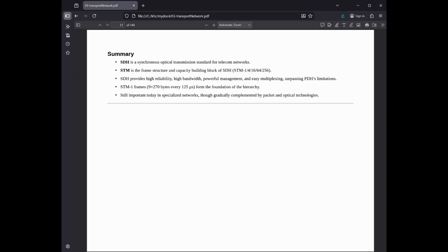The solution: FGOTN allows the network to carve out tiny, fixed-bandwidth hard pipes, down to 10 Mbps, inside a 100G or 400G wavelength. The goal: it allows carriers to finally turn off their old, power-hungry SDH shelves and move those legacy E1/T3 services onto a modern, power-efficient optical platform.